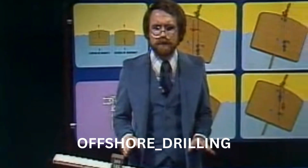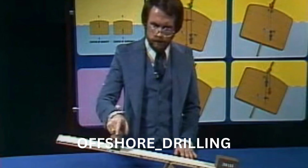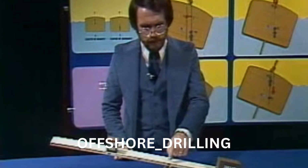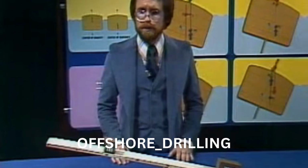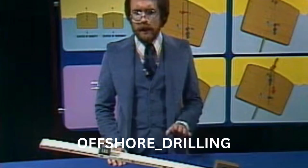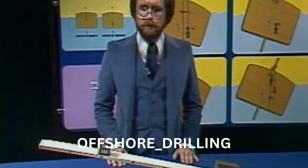Here we have a 100-pound weight 10 feet to the right of point A, and also 10 feet to the left of the fulcrum. A 200-pound weight is placed 10 feet to the right of the fulcrum. How far will the fulcrum have to be moved in order to balance the seesaw? Since the fulcrum is going to be moved, we cannot calculate the moments about point G unless we use algebra. So we will have to calculate about some other point.